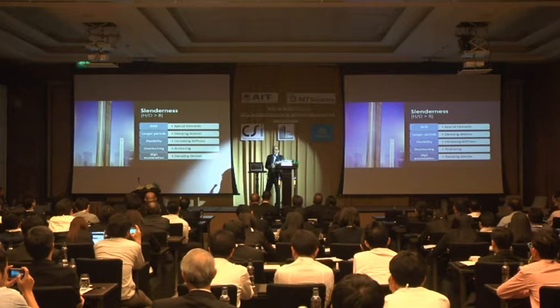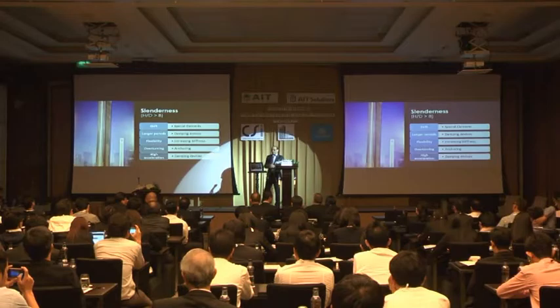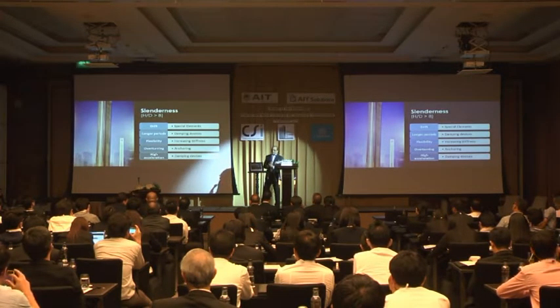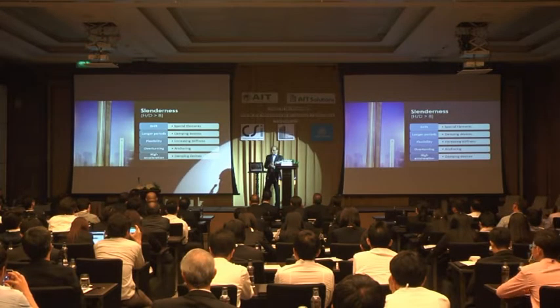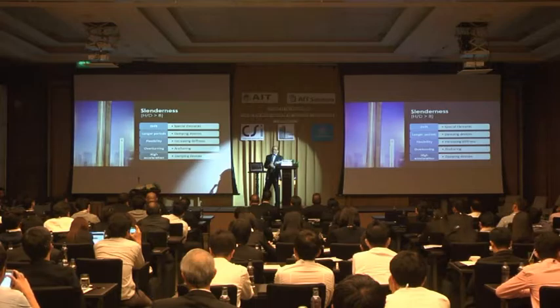We get larger natural periods, which make the building flexible. You need damping devices. We looked at some devices in the morning, interesting applications of dampers. Flexibility, we need to increase the stiffness somehow by adding components, by modifying systems.